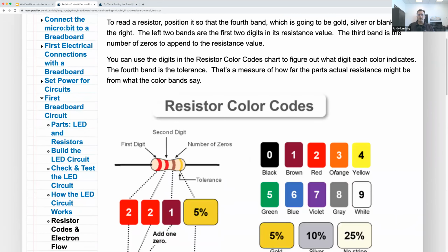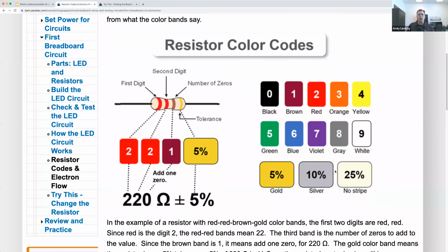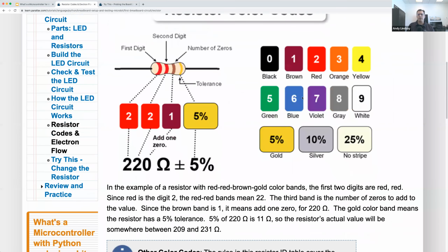Then we talk about the resistor color codes. This is kind of a simplified way of thinking about it. In engineering school, they talked about, instead of tacking a number of zeros onto your resistor value, it being 10 to a power of that number. But the net effect is it's the number of zeros to add. So to keep it simpler at this introductory level, I just called it out as the number of zeros. So we have 3 stripes, or 4 stripes total.